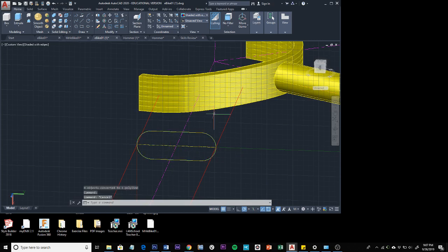Now to practice what we went through in the last exercise, we're going to offset this shape. So I'm going to go to the offset tool, specify the distance, and if you haven't offset anything else, it should already be set to 0.7, which is what we used for the seat pole. So we're going to leave it at 0.7 for the distance. I'm just going to press enter to accept that distance.